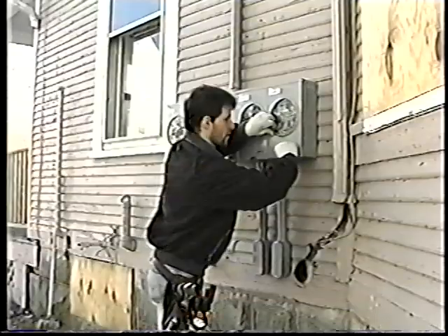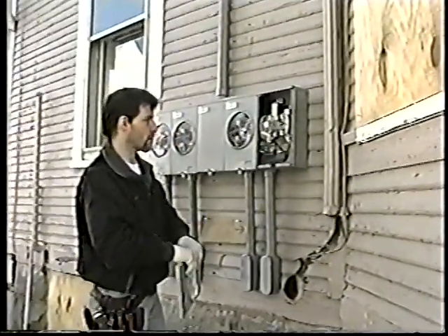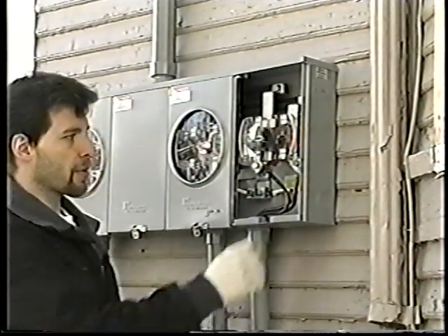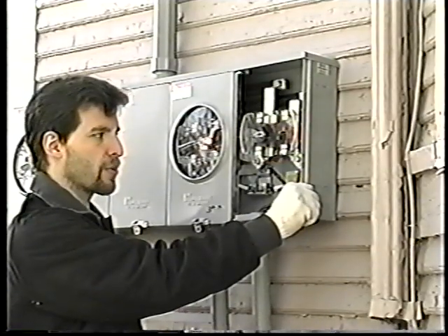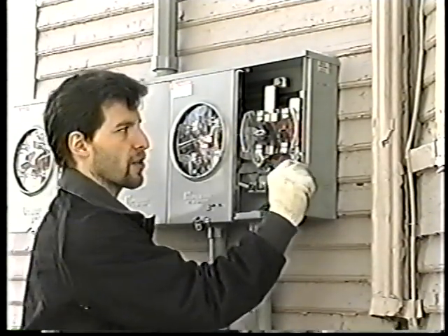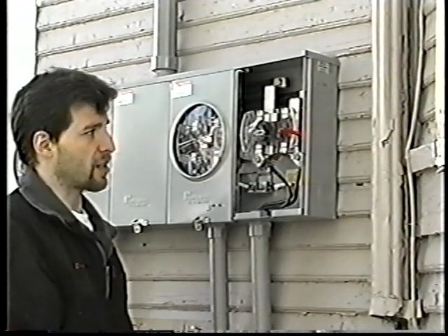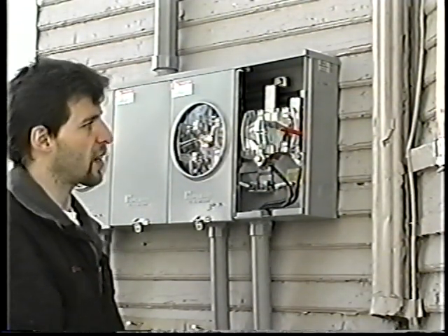So this fourth designation is going to be put in. It was put in for an owner's panel. New law requires that if they remove the meter, the power cannot be interrupted to emergency lighting and smoke detectors and things like that. So they have a little lever which they build into the meter box, which bypasses the meter. So when they take the meter out, the place still has power at all times.